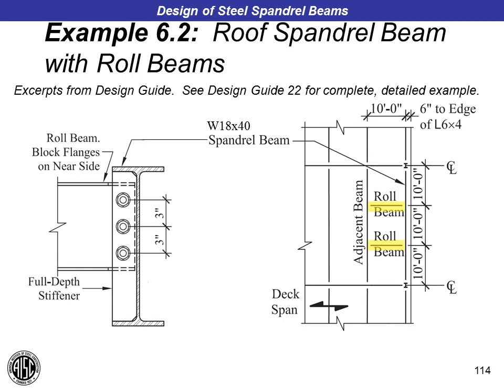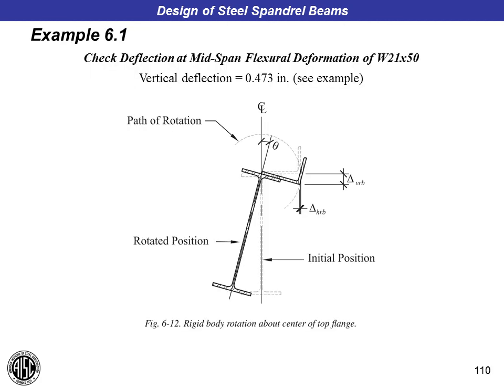Now there's a question on example 6.1. The question is, the rotation is considered here about the top flange. However, do you consider that cases with only a deck and a deck connector are sufficient to restrain the top flange? And I think the question asker is saying as opposed to when there's a full slab involved.